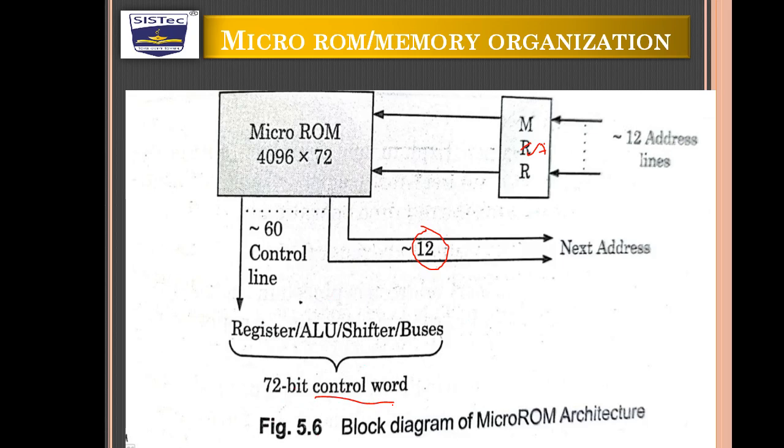The memory of a micro-coded controller usually has a wide data bus related to its address bus, and most of these data lines are dedicated to driving control points within the system. A few data lines are used to provide next address information to the next address sequencer, and these 12 data lines contain the address of the next instruction.